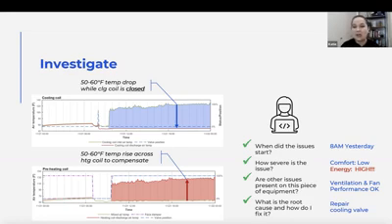So clearly my control system is being tricked, because it looks at this cooling coil and sees that it's closed and says, I'm 5 degrees below set point. I'm going to open up my heating coil and I'm going to go for it. So I'm 100% open in my heating coil, and I still cannot overcome this leaky chilled water coil. It's leaking so badly. I still cannot get to set point. So if we were to leave this going, that thing would just chase it all day long trying to get to the set point. So now I know that energy impact is very high.